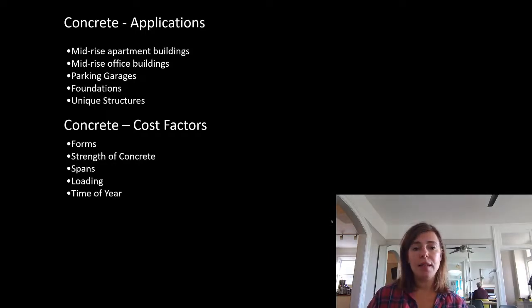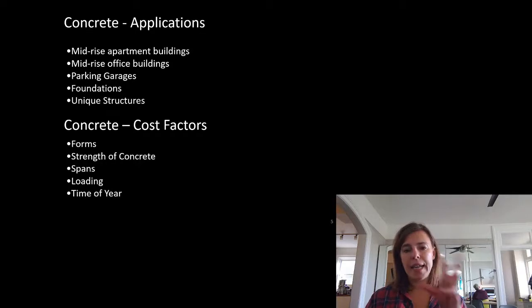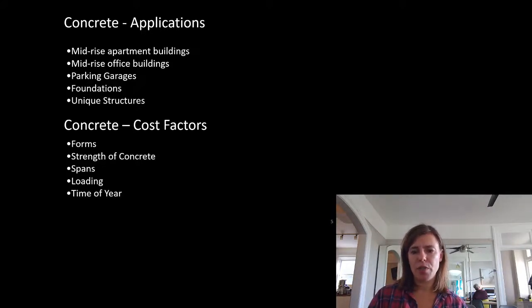And like I said, time of year is a huge cost factor in concrete construction. Too hot a summer, hard to do concrete. Too cold a winter, hard to do concrete. So understanding your peak concrete season has to line up with your construction and the mobility, when you have contractors, when you get your permit. All of those things can add into the time of year of construction and can have a big impact on a concrete building. So those are the quick thought processes of concrete as our construction material.